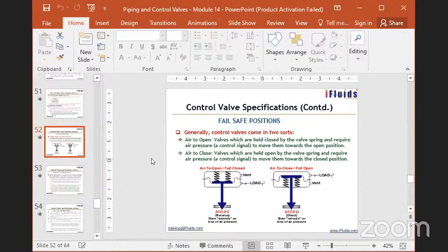Whether you have to make the wall in carbon steel, stainless steel, or any other material, or maybe the body is carbon steel. Inside you can give stainless steel lining or rubber lining, etc. Acids are corrosive, especially dilute acids are very corrosive. For dilute sulfuric acid, hydrochloric acid, they use mild steel with rubber lining. Rubber does not have any mechanical strength, so you have to have an outer metallic pipe. Inside you have the rubber lining.